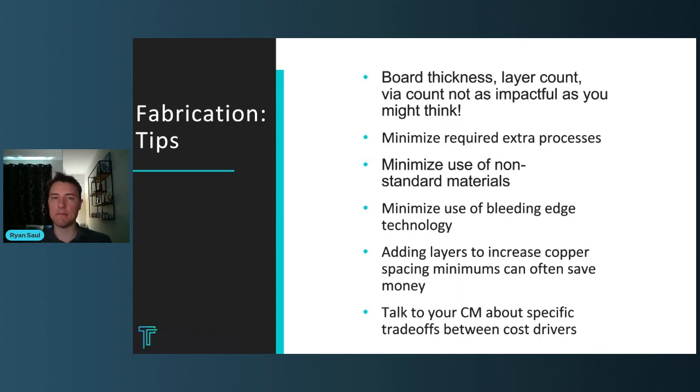Of course, it's done all the time, but hitting your precise targets that you design digitally is in most cases more expensive and time consuming than the fabricator using their experience, using their readily available material to create successful impedance targets using some flexibility. So if you can allow it, if it's not a hard requirement, I highly recommend setting control impedance targets and allowing some flexibility in dielectric as well as trace dimensions.